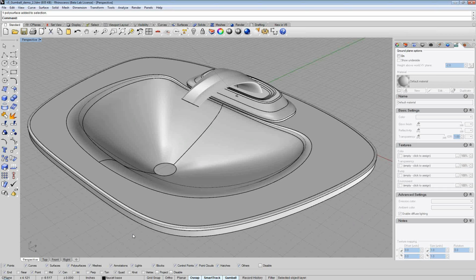And personally, I like that sharp edge because that's one less pass that, say, a mill would have to make. But if you needed some sort of draft to pull out of a tool or something, then depending on how that was made, yes, you'd have to go into that interior part and fillet or blend that edge separately. One other possibility is to simply shell it after the filleting.